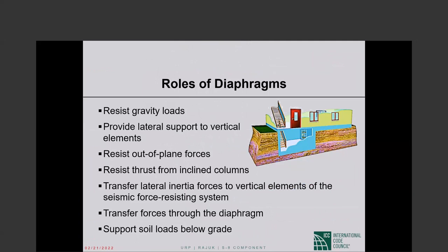These are the different roles that diaphragms play. This is gravity loads, not acting as diaphragm, acting as slab, but anyway, that's a role. Provide lateral support to vertical elements. That is important. Laterally, diaphragms provide lateral supports to frames, shear walls, and so forth. Resist out of plane forces. I don't know any difference between the first item and the third item.